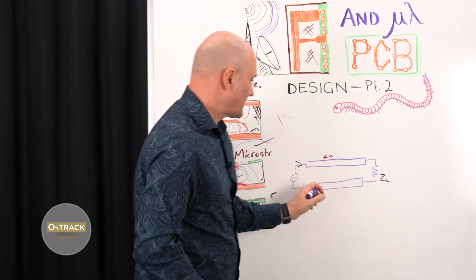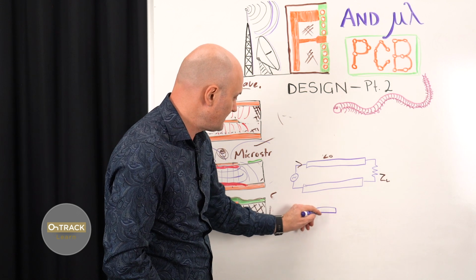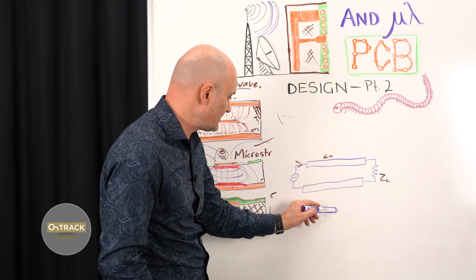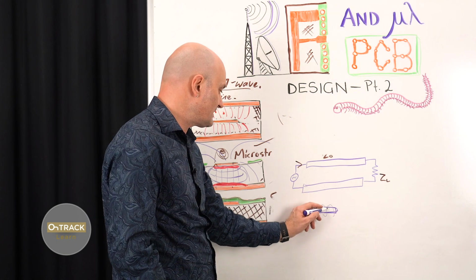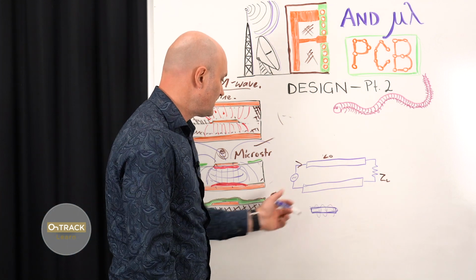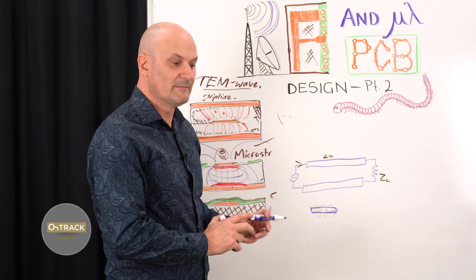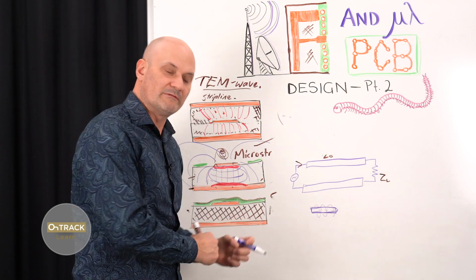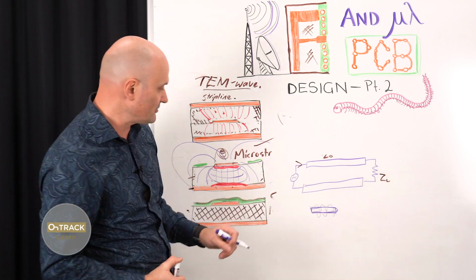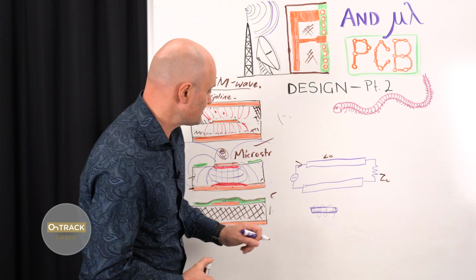Okay, so the way of looking at this is there are conductors, and a conductor, a piece of copper like this, which could be a section of trace, has inductance. So when current is flowing in a particular direction, a magnetic field is set up around the trace. When it flows in the other direction, the field reverses. Energy is stored in that field, and it takes time to set up, collapse, and reverse those fields, right? So there's some delay to this, and that delay depends on the dielectric, and it depends on the characteristics of the metal conductor and other materials around it.